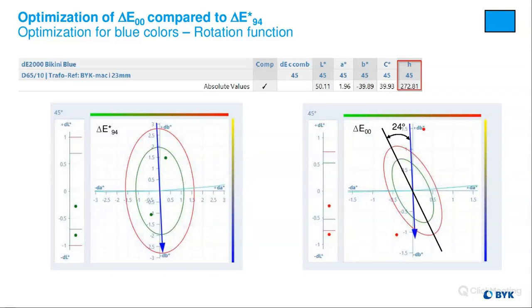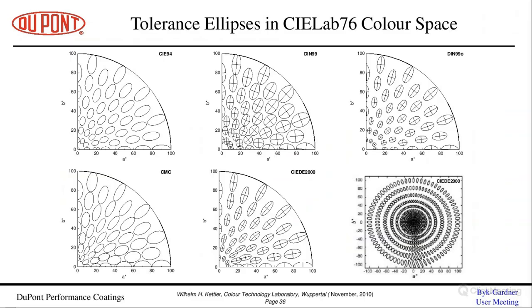And the delta E2000 on the blue colors will match more what we see visually. When we see something and we think it should be rejected, the delta E94 could pass and the delta E2000 might fail it. So it's not something that we don't see in the industry. It's definitely there, and it's something you need to be aware of when you're looking at color equations to set up for your color program.